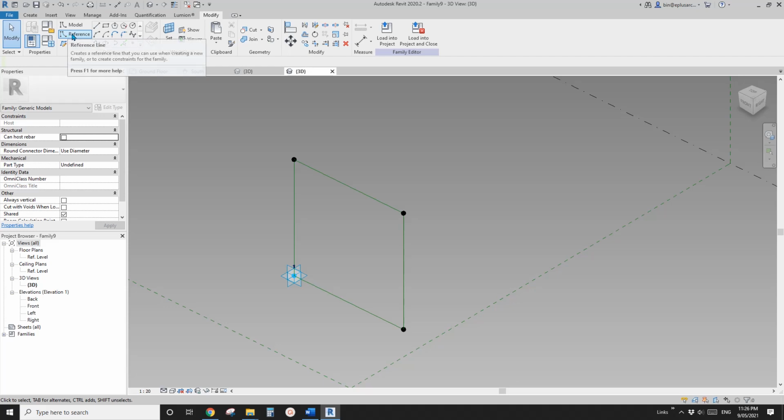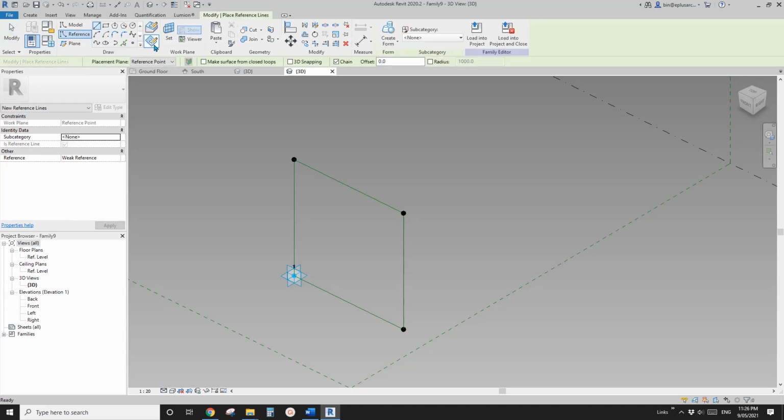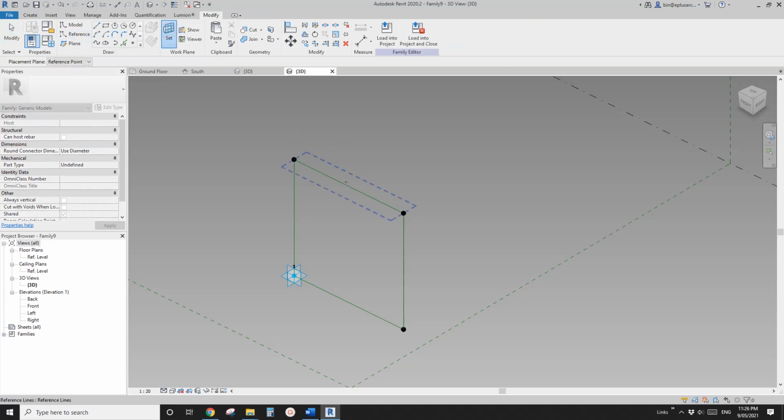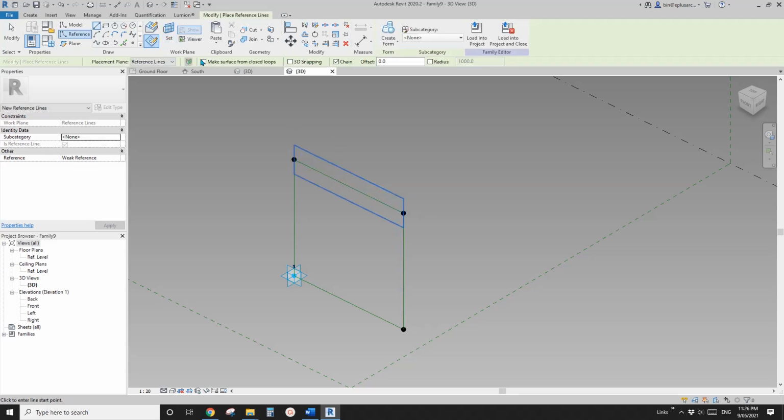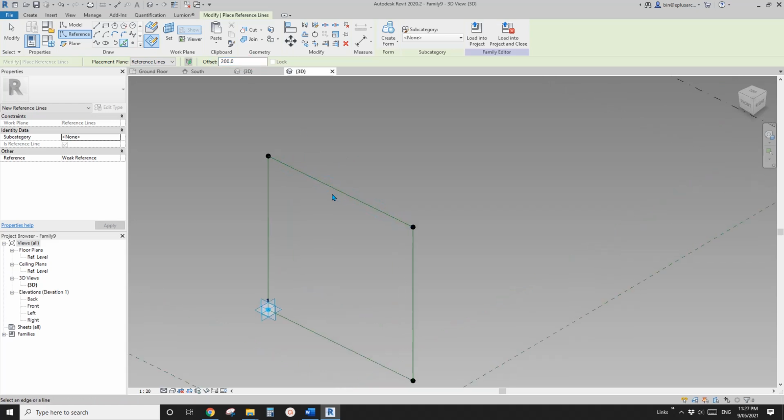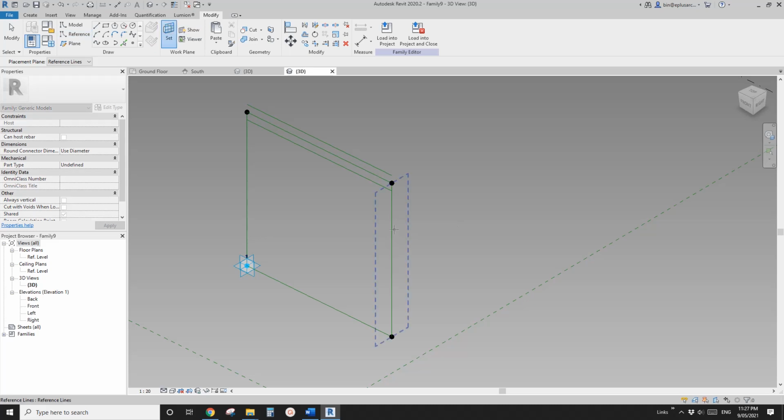We can use a reference line this time. So draw, set work plane and pick the vertical work plane of this reference line, and use pick line, offset by 1. So for example, if I make it 300 thick, maybe make it 400 thick. So it'll be 200 on 200 mil each side. So here, up, down. So once again, set work plane on this reference line.